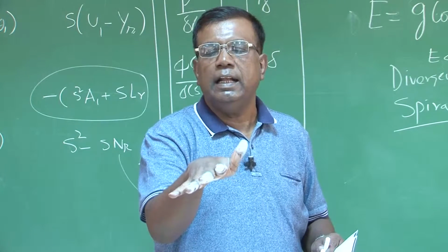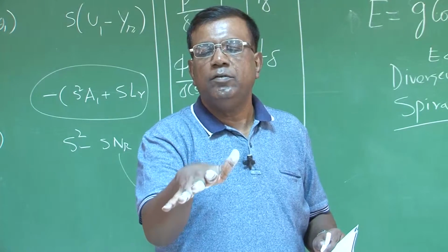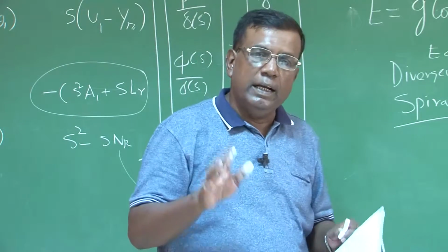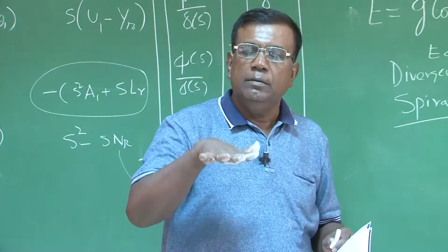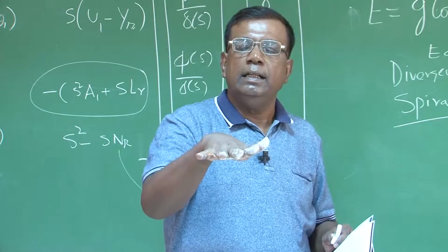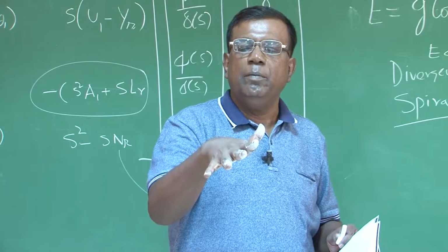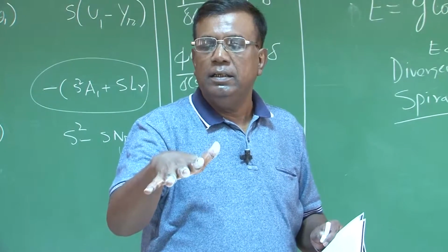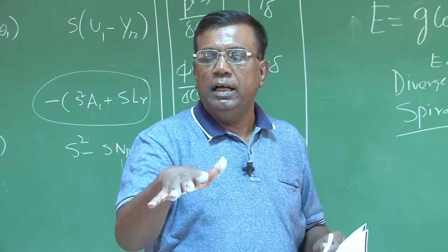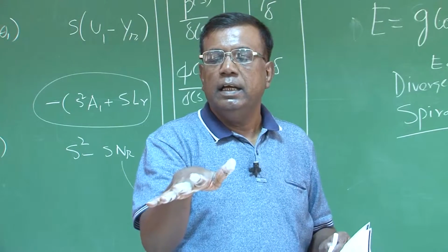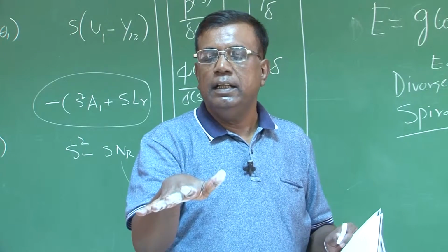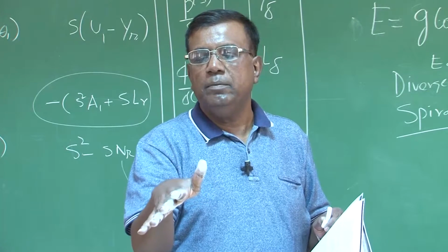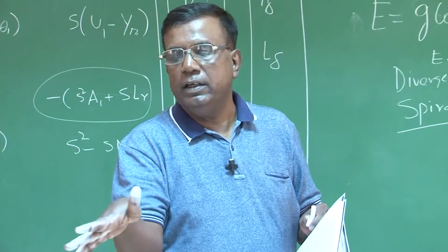As it turns, the left wing gets more relative air velocity, so it further banks and again further turns like this.